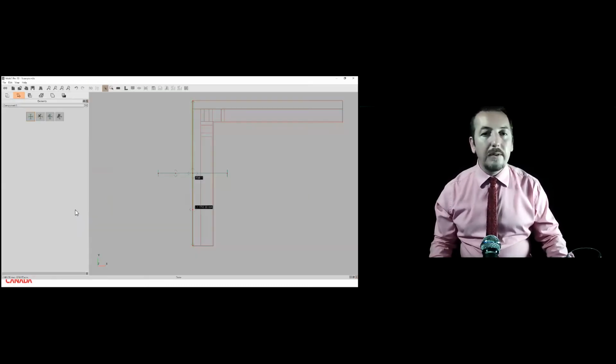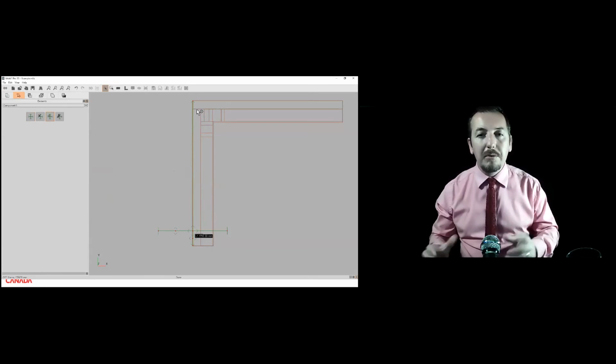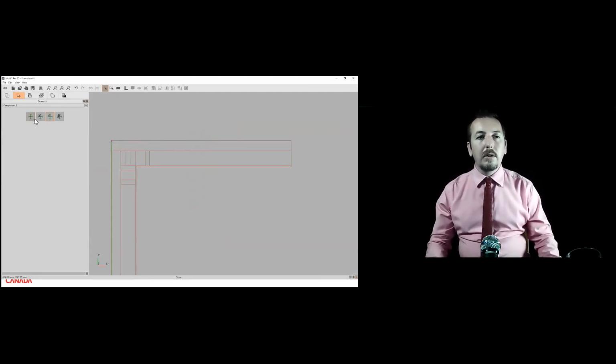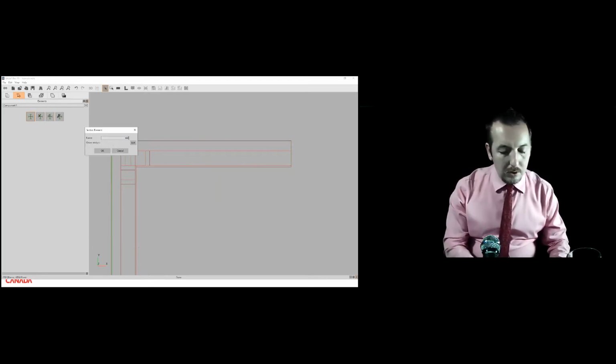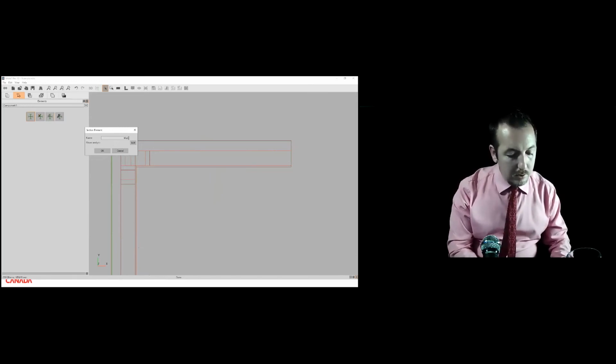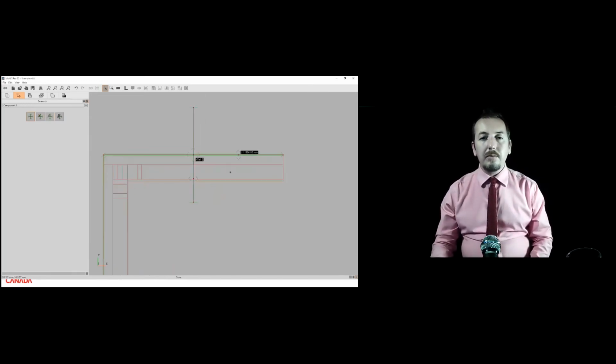So what we want to do is, really, you can move this down here just to make it visually correct. Take the U value at the end of the section and apply it to the whole thing. That's what PHPP would have assumed. That's what we're taking away. And the difference we're left when we do this for both sides is the influential heat flow at the corner. Okay, so let's do the other one. That's all I need to do.